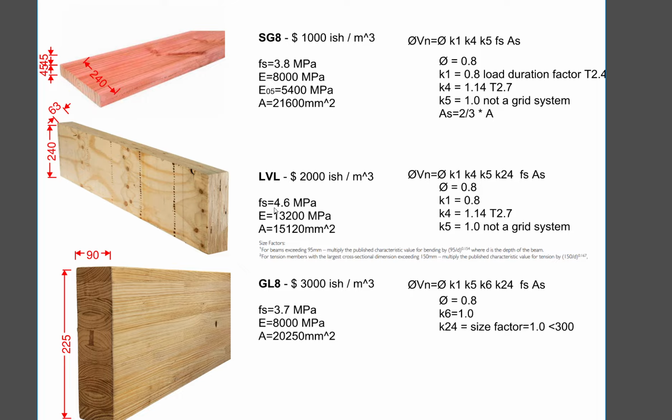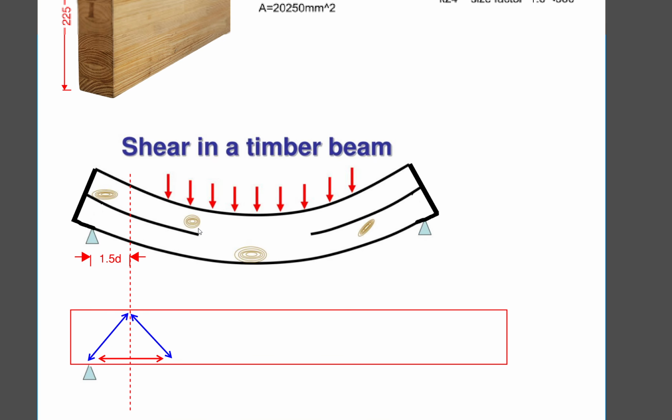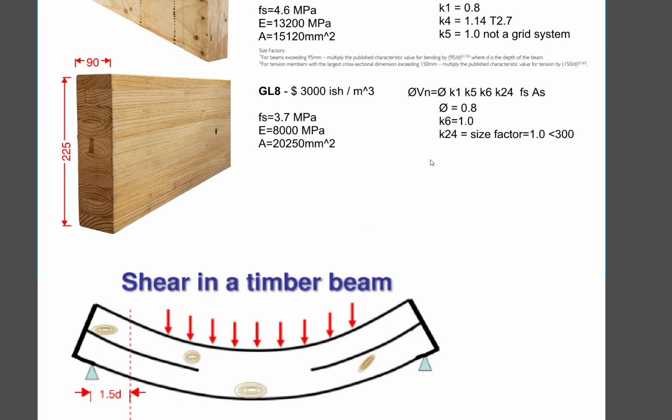It's slightly higher shear strength than the sawn timber and the glulam, because I reckon it's the mechanism forming when trying to split. It is difficult to split through the laminations of a vertically laminated timber, rather than when you have these parallel grains. It's easier to split starting from these grains. I reckon that's probably the reason. So that jumps into the shear mechanism. That's what we need to understand before we jump into the calculation equations.